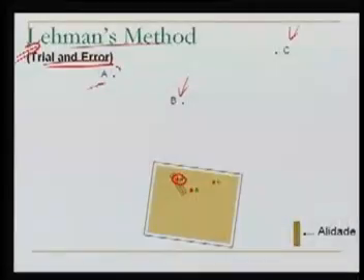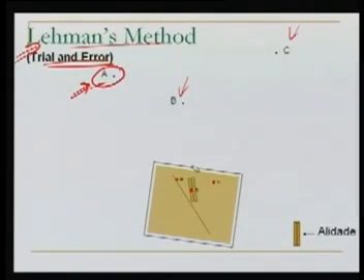The table is clamped. The table is not moving. I rotate the alidade in order to bisect capital A. Let's do it. Okay, it is bisected, and I draw a ray, a resector. Well, the resector is drawn here now. Similarly, I do it for B. I do it for C also.